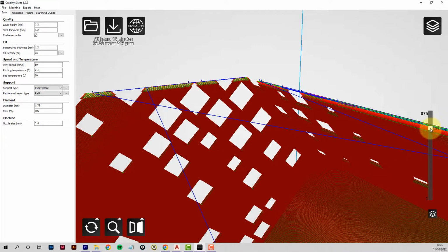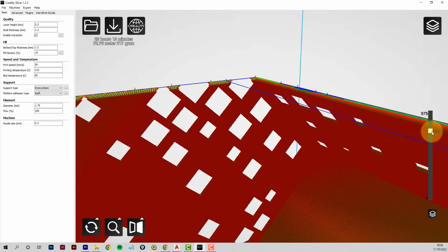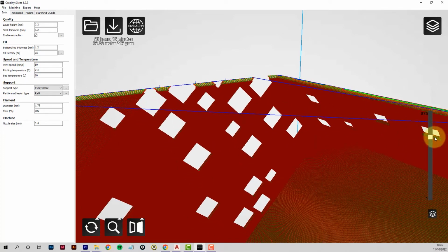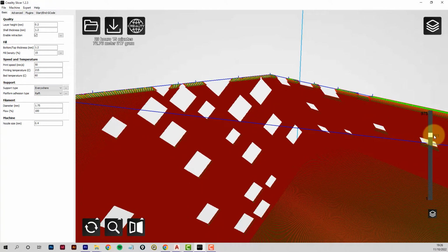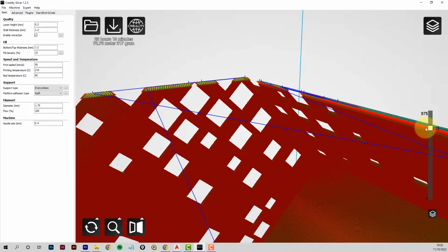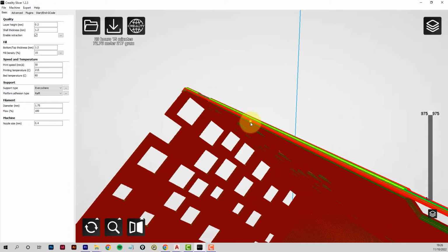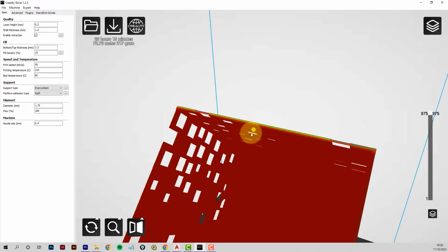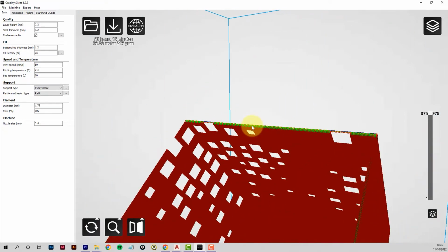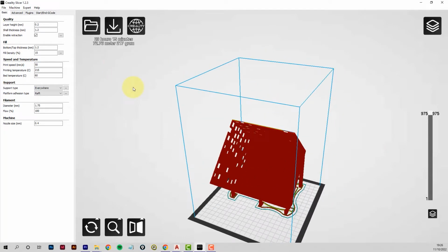Okay, and that's another. In that way, it can avoid doing the infill. So we're seeing quite a lot of blue lines appearing in the window openings there. Those are a line thrown across to help it start creating the window heads, the lintels. That's called bridging. If it's not too far and it thinks it can do it, it will have a go. But if the gap's a bit too big, it chickens out and has to put in some scaffolding.